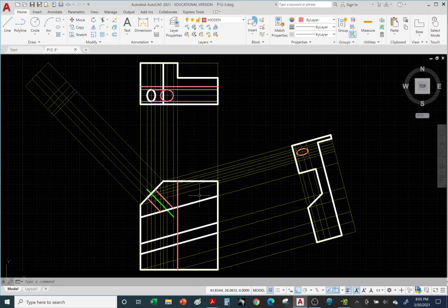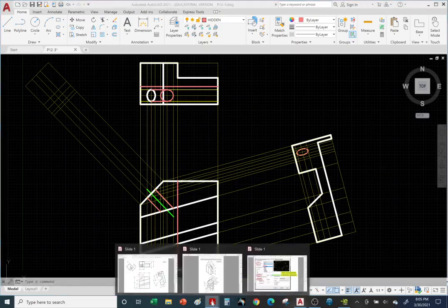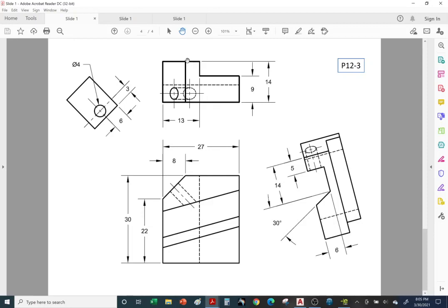All right, so take a look at the construction line. My mistake at the answer key. All right, so we got everything at the top. Oh, we're still missing the green center lines. So we'll do the green center lines. Okay, this one has its center line already. So we do have to put green center lines or center marks for ellipses also.